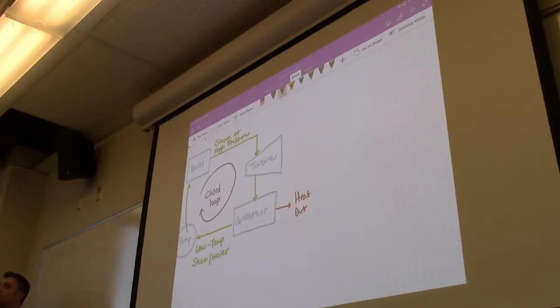Have you ever heard of the term a cogeneration plant? So cogeneration is essentially this idea that we take this heat and we run it to another smaller generating unit and repeat the same process. A generating unit that doesn't potentially need that. So this main unit that we have requires steam at very high pressure and very high heat. Then we take the heat, which is not going to be as high, right? Whatever it was X degrees before, now it's X divided by 2. And we'll route that to another smaller unit that can run at a lower temperature, but still generate some electricity. So that's one option, is to take this heat and run it to a cogenerating unit.